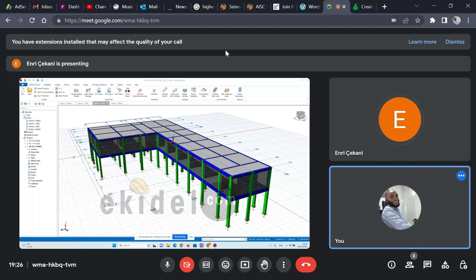Then two, you have to use a high grade of concrete. That's another one inside increasing the capacity of the compression zone. Then also you have to use strong confinement. When I say confinement, it might look a little confusing, but when you are designing a structure against earthquake, you must deal with confinement. Let me use a typical example. You know that for any seismic design, you must tie your columns on the ground with a ground beam, so that it can be able to transfer load evenly. So that beam under the column is serving as a confinement.